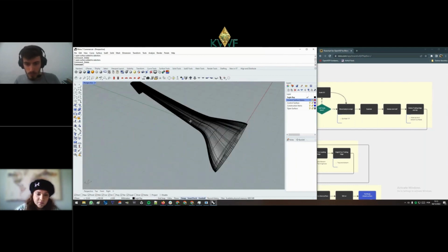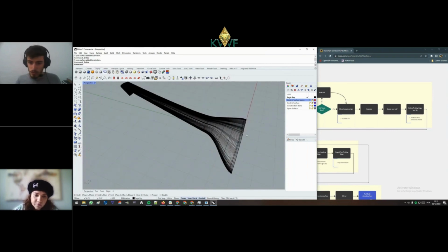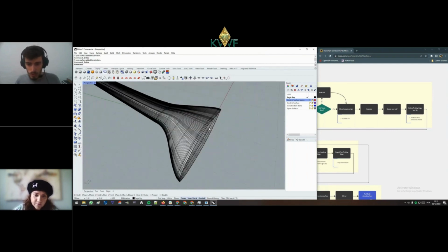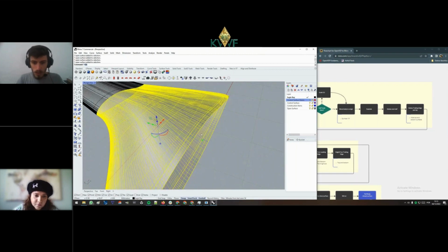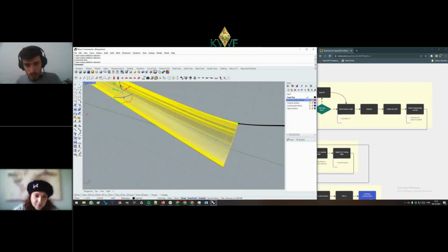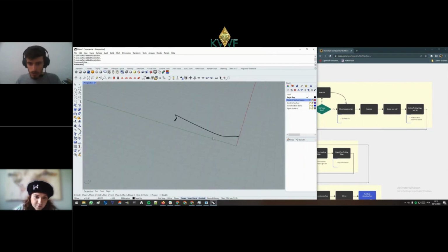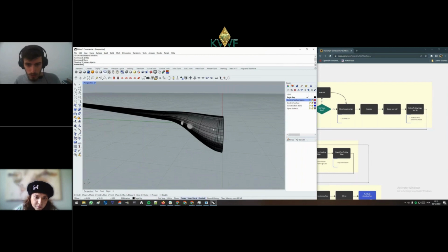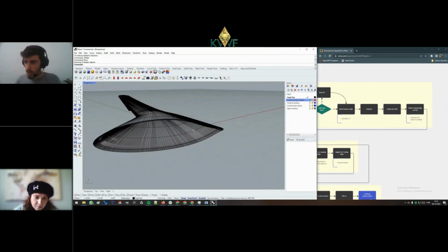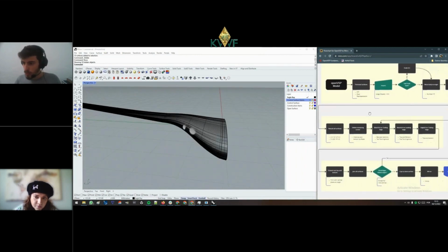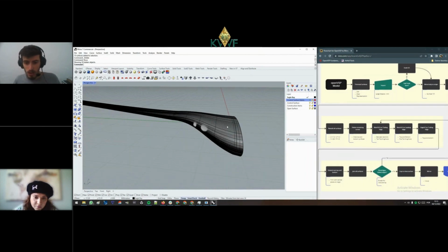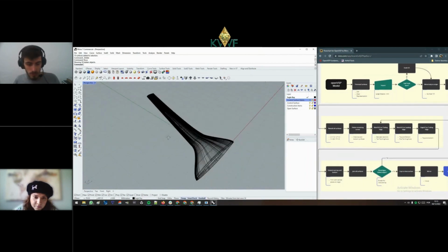For us to be able to actually work on the surfaces, we have to hide everything, and then we will delete the trailing edge and the tip, because those we will reconstruct later. So I can delete everything, show again. This is our half body without trailing edges. And now we move into the second section, which will begin by rebuilding the surface.